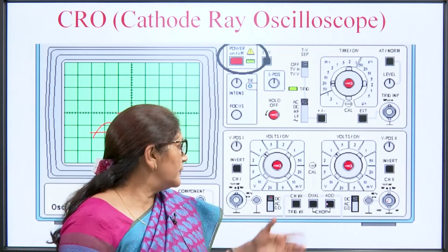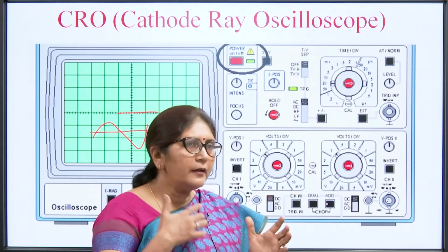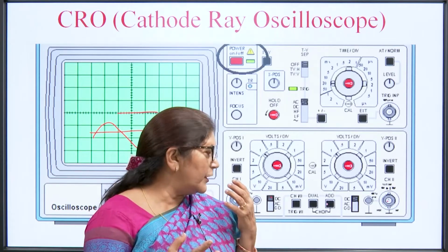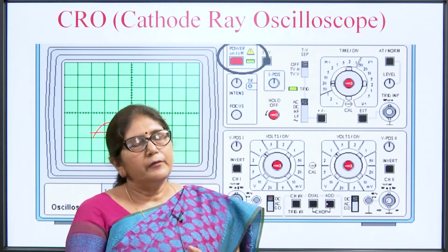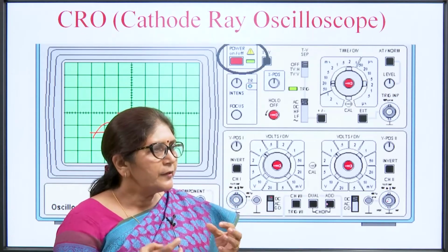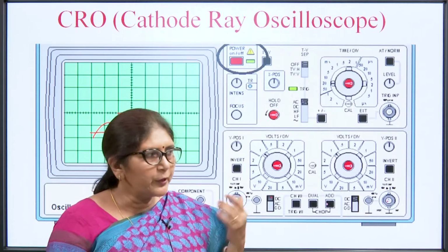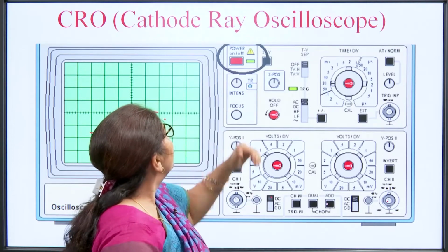So, similarly, we will see both the waveforms on the screen, although it is alternatively fed to the vertical deflection plate. In chopped mode, basically a multivibrator is used and the switching speed is very high with respect to the alternate mode. Then there are so many switches also.